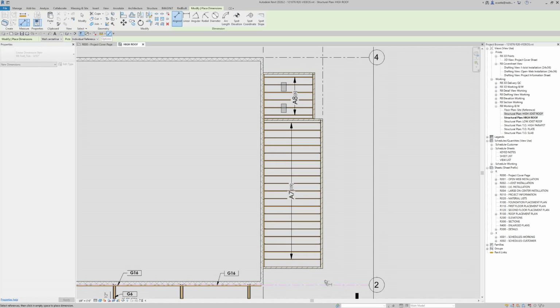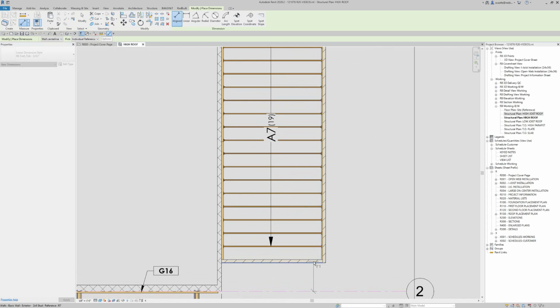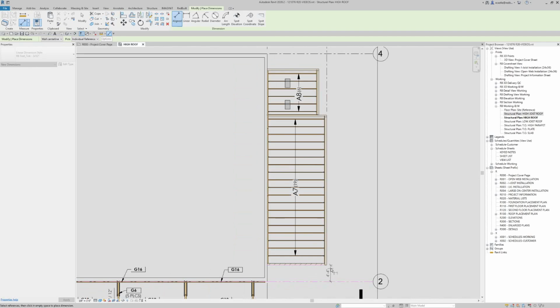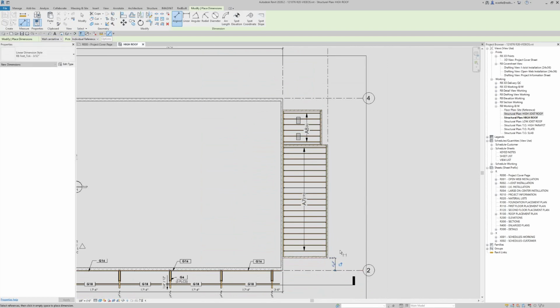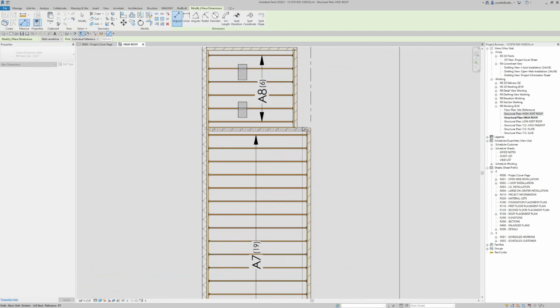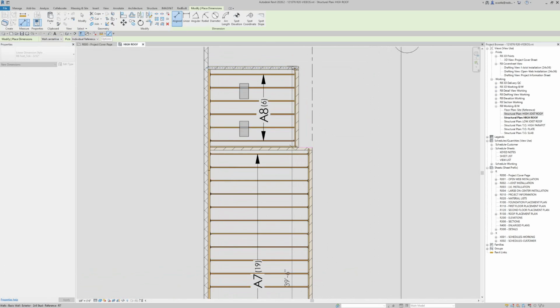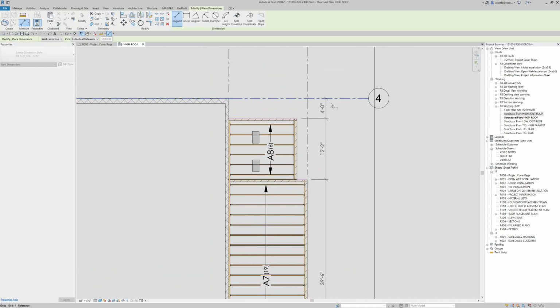and start selecting our joist using tab select to find the edge that you want, and we'll go from base of stud here. And you can either have just one, or you can do a chain and quickly do a whole chain of dimensions using tab as needed to select the face you want.